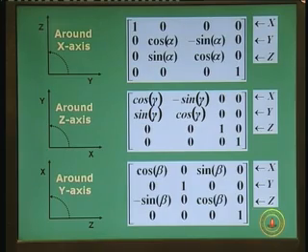Any one sign reversal should have been okay. Here it is done for rotation about the y axis, where you want the rotation to happen from z to x instead of x to z. I repeat again, if you had put a negative sign here, like the previous two cases, in the third matrix first row, if you had put a minus sign on beta, you would have had a rotation from x to z, which you do not want.